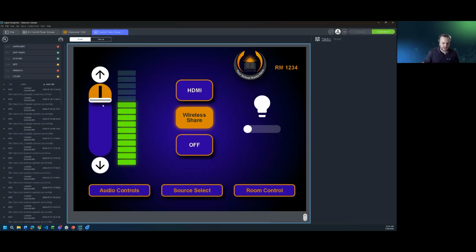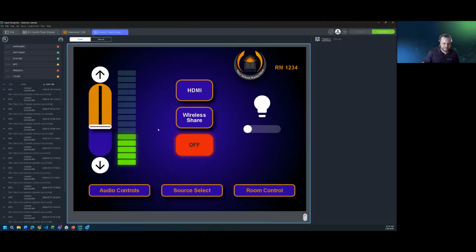I know exactly what it's going to look like for that user. I can even adjust this down to check if this control is right, to where I know that this is actually controlling audio passing through, and it's going to actually affect the audio in that room. So again, another useful tool in DesignOps to help you flush these problems out before you ever go to site, before you ever even have a DSP in hand. There's a lot of internal testing you can do here.